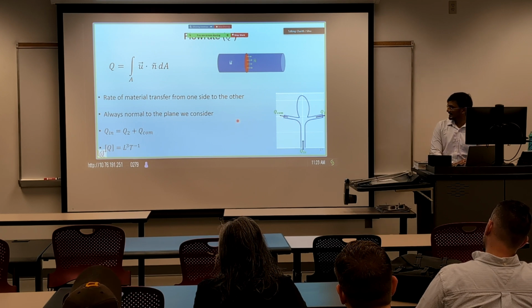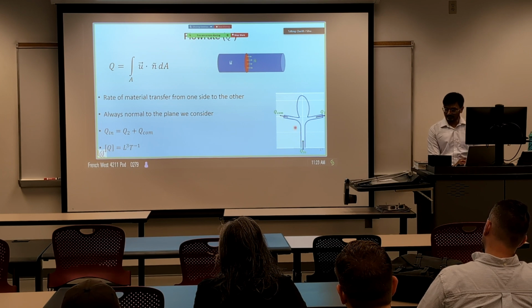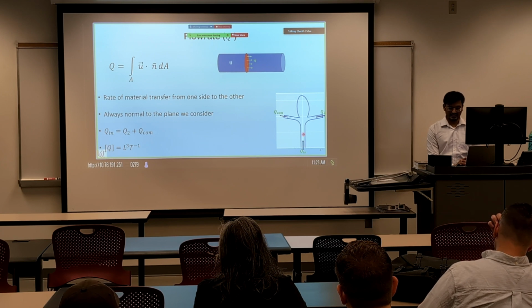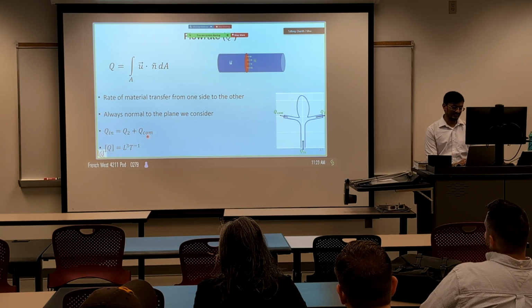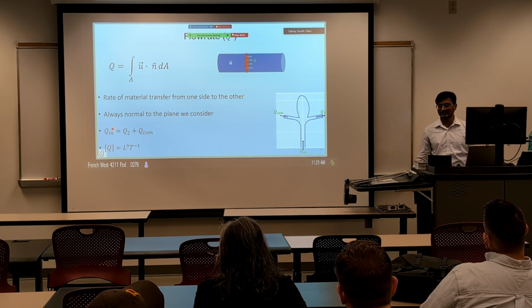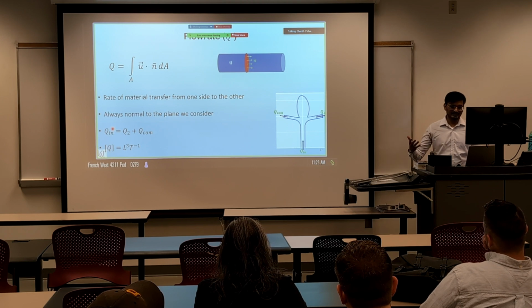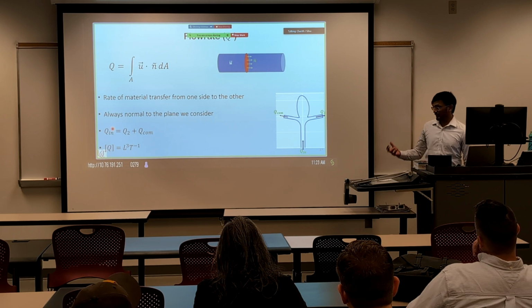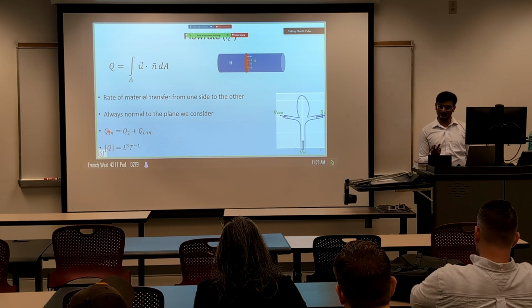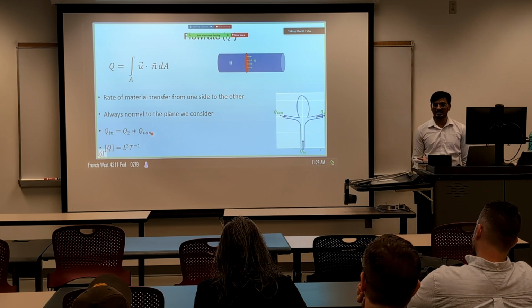Now this is an important point. In our domain, we have an inflow from A1 and we have two outflows. Since mass is conserved, we have this relationship: whatever comes in should go out. So if we know two values, that's enough, and we can evaluate the other value. Later on, I will be talking more about flow rates. I will only mention two flow rates because the third one can be calculated directly.